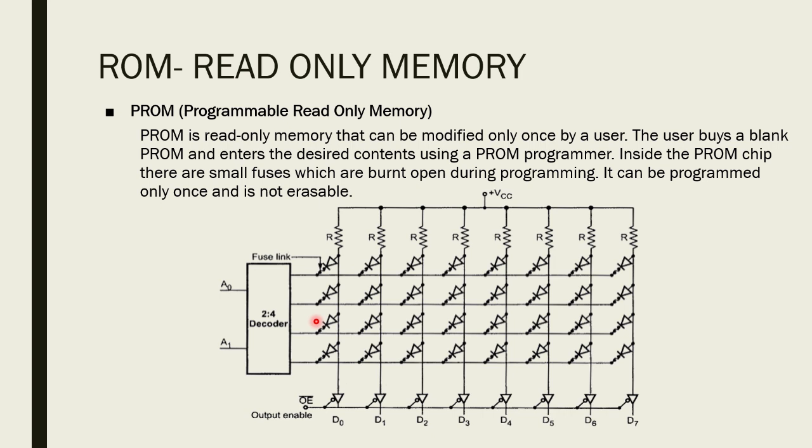Here, the programmable read-only memory uses a p-channel depletion mode MOSFET. The procedure allows the user to program the PROM in the lab to achieve the desired relationship between the input address and the stored words. Special instruments called PROM programmers are available commercially to facilitate the procedure. Once programmed, PROM is fixed and cannot be changed. If the pattern is to be changed, the unit has to be discarded.